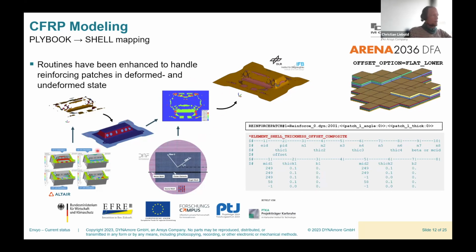This optimization has been done on the final structural part. So what we had to do is get this information onto the final structural mesh, and then through the usage of the deformation gradient, we could calculate the reinforcing patches and the respective orientation of these patches onto the blank sheet prior to the forming process. And we also overlapped that with the results of weaving simulations.